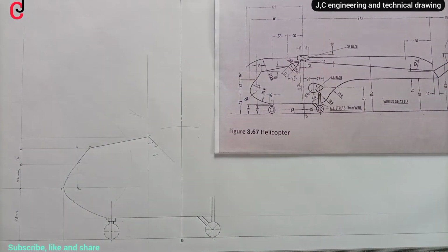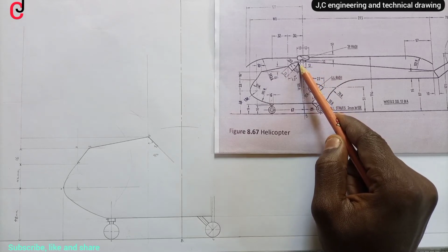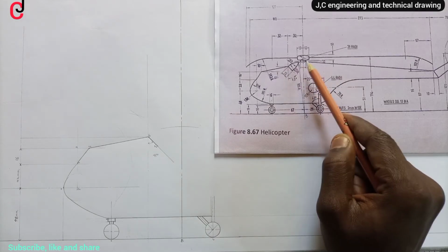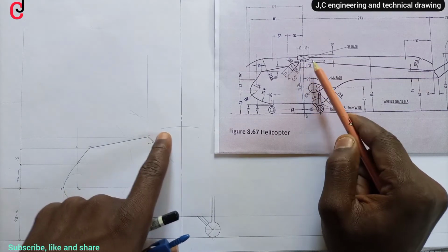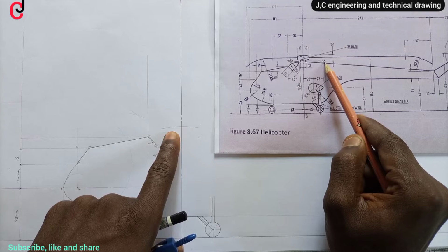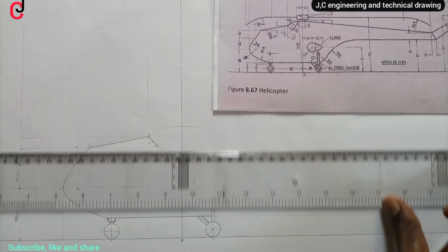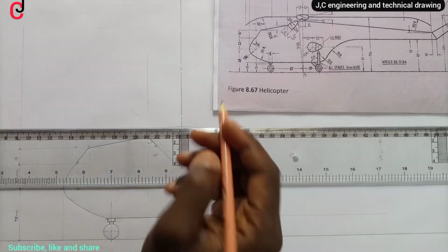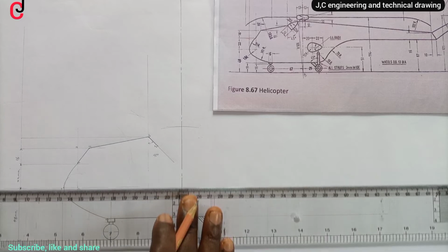Now, from our diagram, we're told that the distance of this point of the arc proceeding from our vertical line towards the left is given to us as 10 millimeter. So what we need to do, we'll project the arc, the construction line, just to pick 10 millimeter radius.